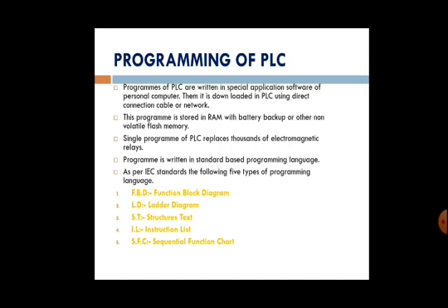As per IEC standards, the following 5 types of programming languages are available. First one is FBD, function block diagram. Second one is LD, ladder diagram. Third one is ST, structured text. Fourth one is IL, instruction list. Fifth one is SFC, sequential function chart.